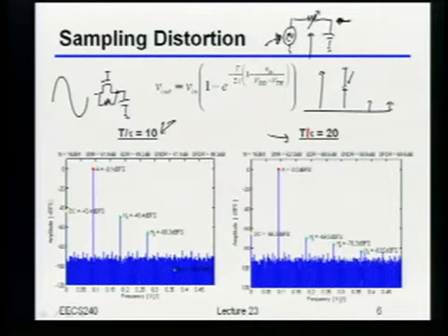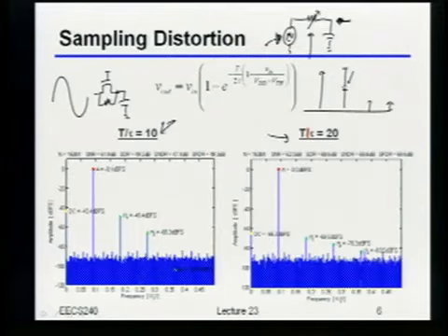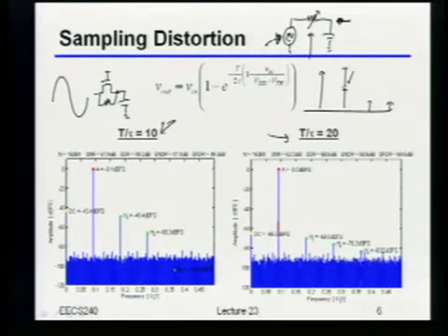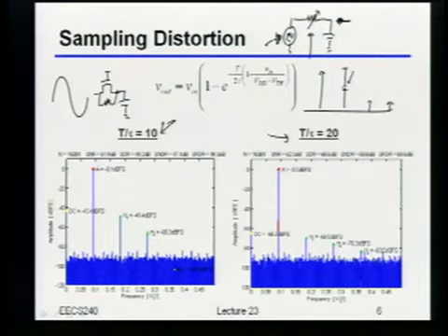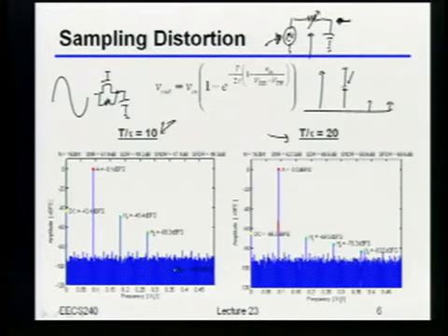So by the way, anything else that you can do to maybe make this a little bit better, other than really modifying the circuit in a huge way? Anything else you can try and change? If this is really what's totally limiting you, anything else you could try and change, other than just brute force sizing up the switch? What's causing the variation in the resistance? This is changing. Yeah, the VGS is changing, right?